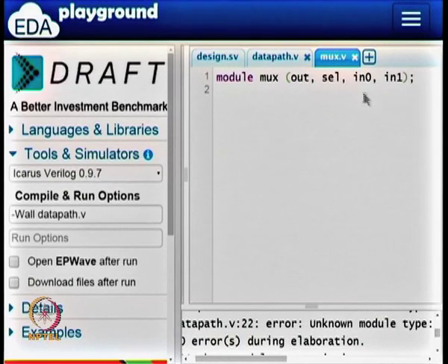These names in0 and in1 are local to the multiplexer's description, that is it. We have done this before: in0, in1, select and output. These are the 4 ports that the multiplexer has. So let us do the descriptions for the ports. Output, so out is actually a 7 to 0 output.